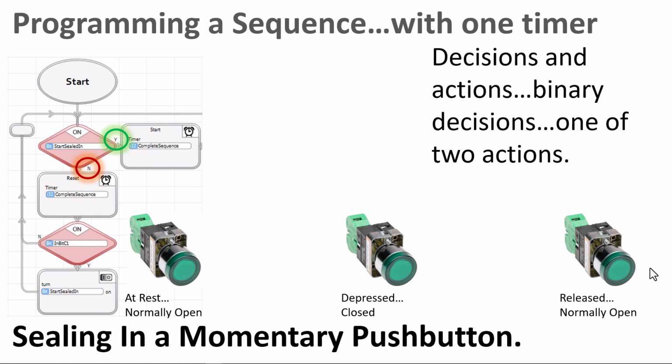Now go back to the top decision that says, is start sealed on? Start sealed in, is it on? No. Reset, is the push button pushed? No. Then it goes back to the top and it just sits there and it cycles between those 3 instructions. When you power up your little controller here and you haven't pushed the button yet and you leave it this way for a week, that's what it sits there and does for a week.